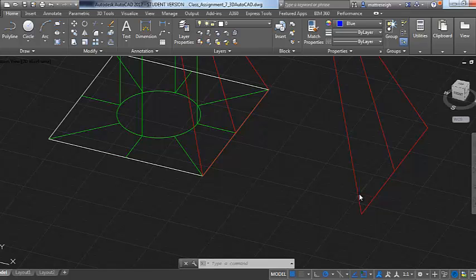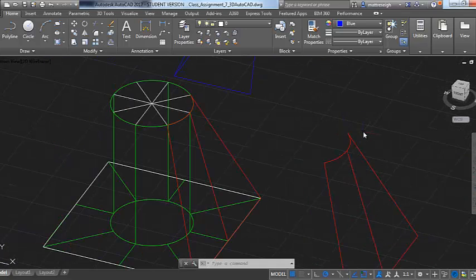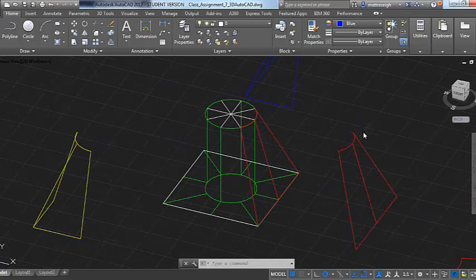I know that's not going to be super obvious to a lot of you, and it would take a little bit of press brake experience to see what I'm talking about, but that's about the only disadvantage I had to doing this. It does put 4 weld seams in something too, so maybe if somebody was worried about distortion, I have a weld seam in every corner essentially when I do this.